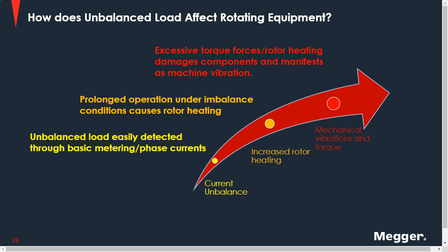You can see that easily, that it's an unbalanced system. However, prolonged operation under imbalanced conditions will cause rotor heating, and we're talking specifically about motor protection here. This will end up propagating itself as excessive torque forces and rotor heating, which damages the components and eventually manifests itself as machine vibration.